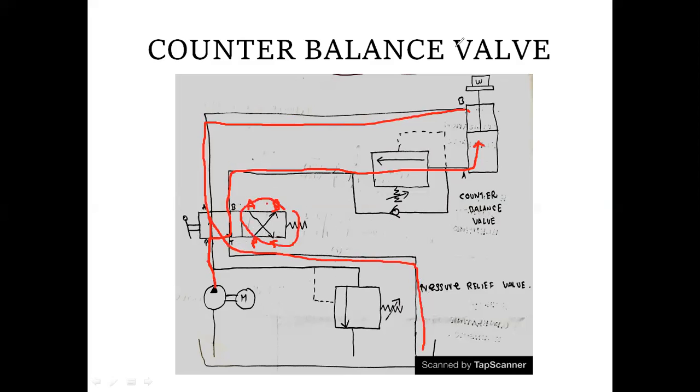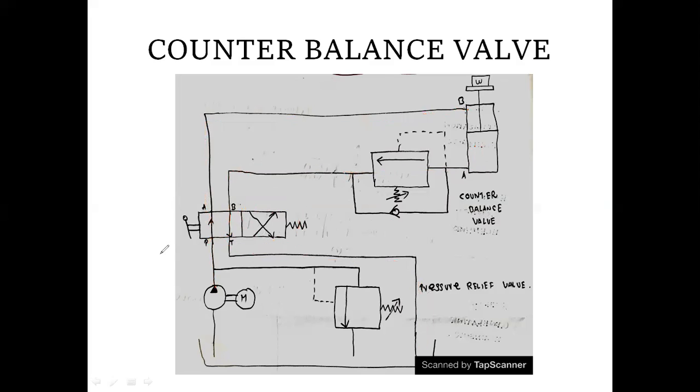So this is why the valves are in this position, right? So this is the general working of this circuit diagram. But what happens in the second position, when the flow goes this way and enters the actuator? It pushes the piston down. According to the gravitational force, the weight also acts downward. When it acts downward, there is a chance of damaging the parts over here.